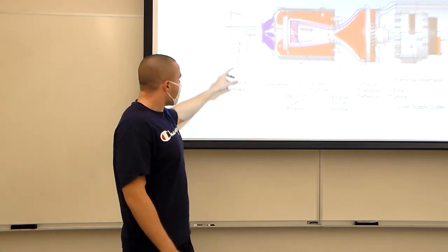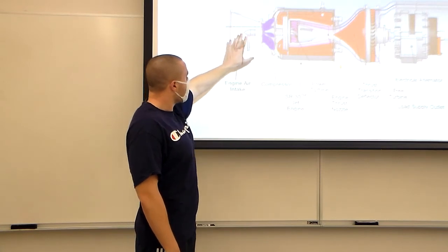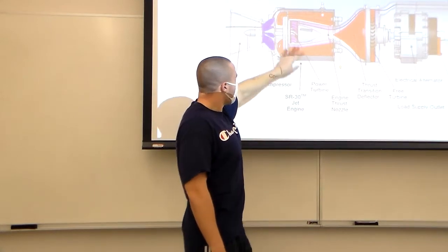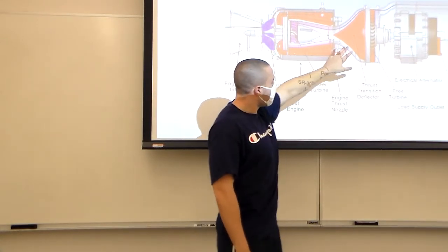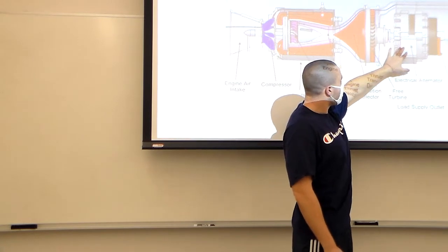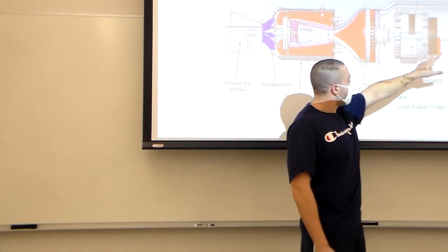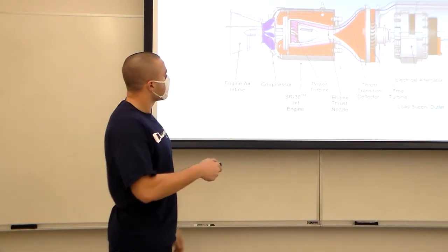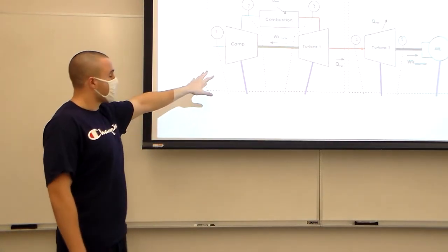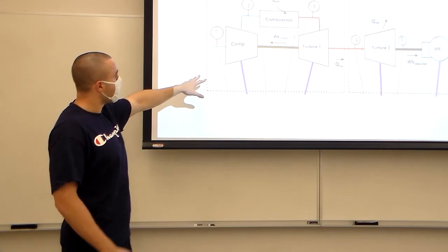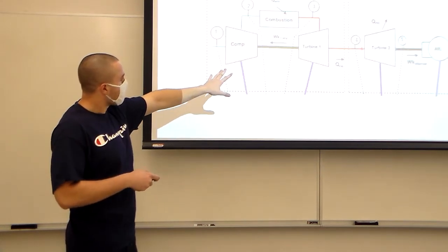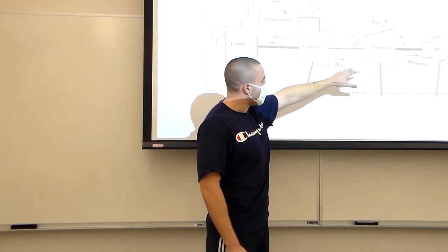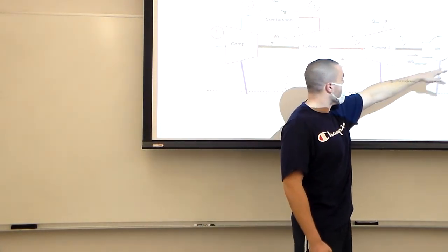So, I know Bryce went over it, but a brief little overview again. So, compressor inlet, compressor itself, compressor outlet. This is going to be our first turbine, our second turbine, our generator. This right here is a free turbine. This is the outlet, and this is the inlet. So this is a simplified schematic of what I just showed you. So, a brief look at this. You have your compressor, your combustion area, your two turbines, your generator, and your power output.